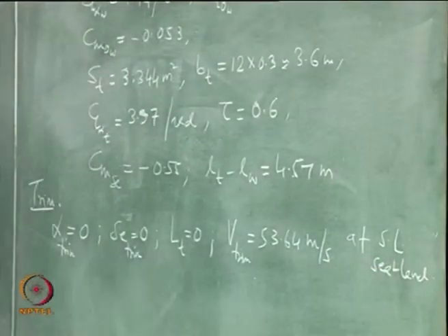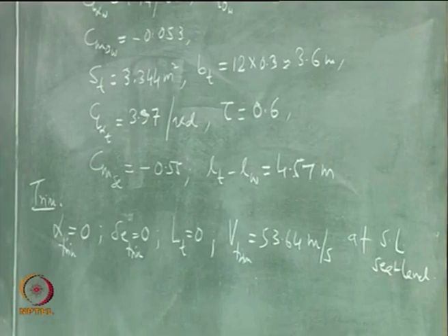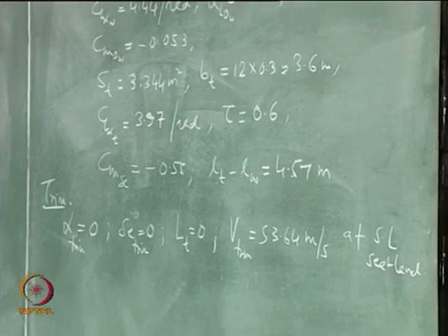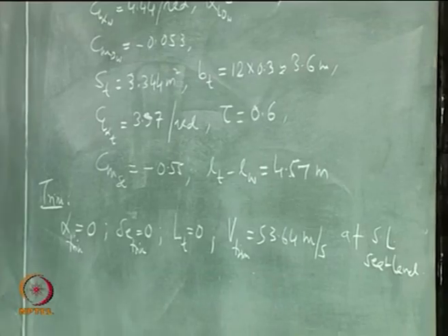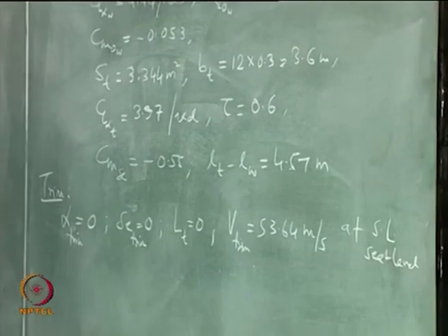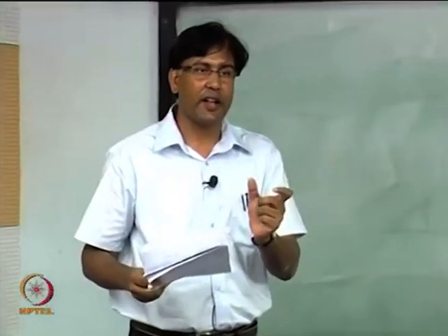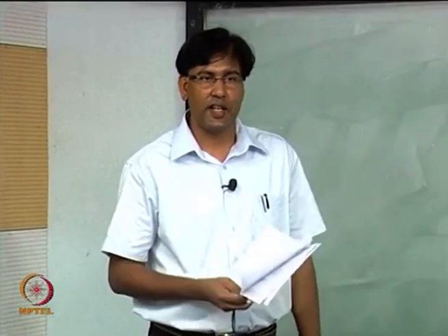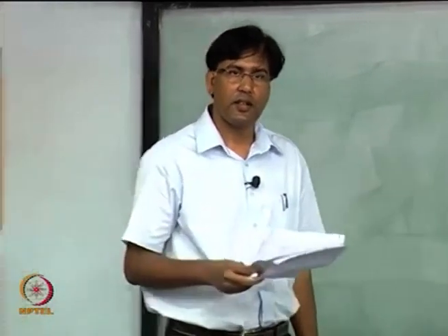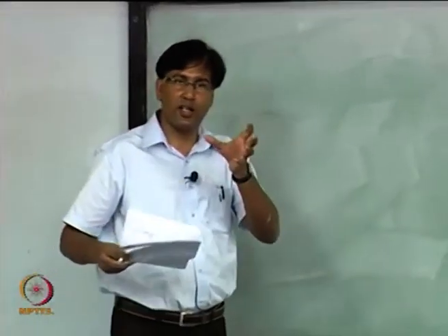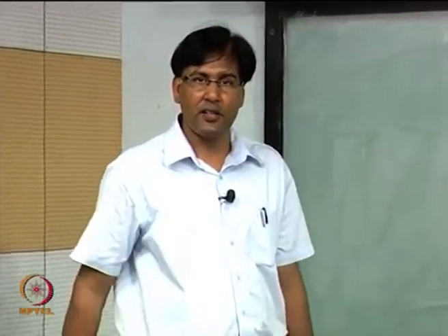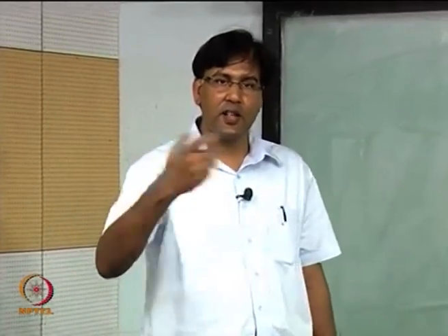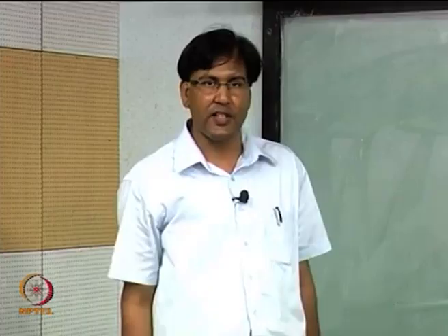Sea level condition. So, we will also assume that the aerodynamic centers of tail and wing are lying on the fuselage reference line. So, there is no moment created because of the vertical distance, and CG is also lying on the fuselage reference line.